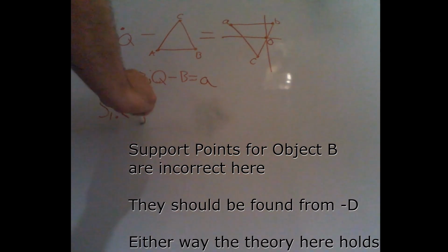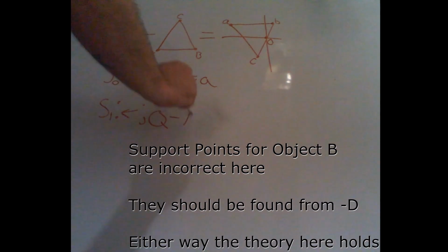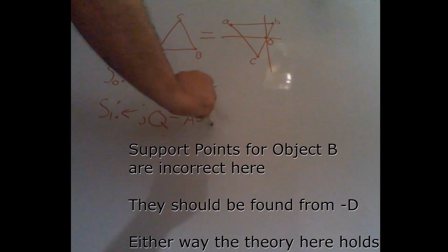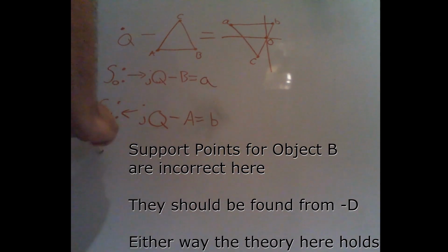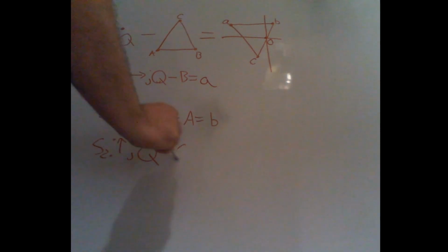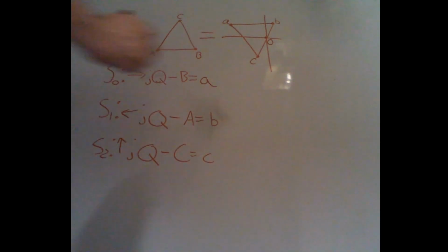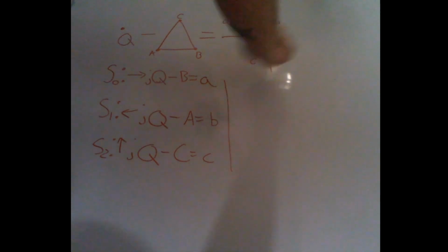We do not compute the entire CSO, however, we do it one point at a time. We do this by creating a 0 to 3-dimensional simplex to represent the current inspection of the CSO. Every time we add a point, we evolve the simplex until we either terminate or detect containment of the origin inside the configuration space obstacle. This solves the first goal, determining collision.